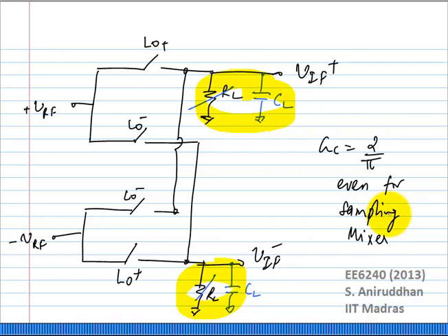You do not have a return to zero in the case of the resistively loaded mixer. And so the load really does not do anything because you are looking at the output as a difference between those two nodes. You are not floating any node at any time. And the same thing goes for the capacitively loaded mixer also. And so the gain is actually lower by around 5.5 dB compared to the single balance mixer.